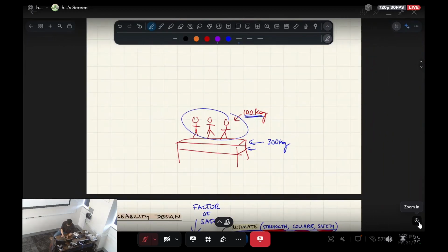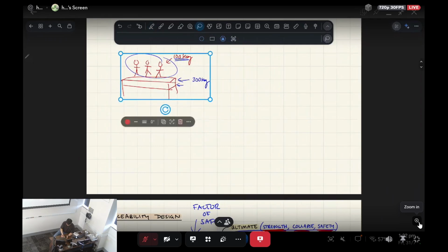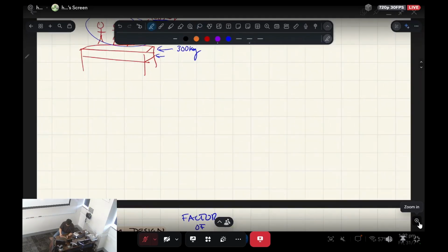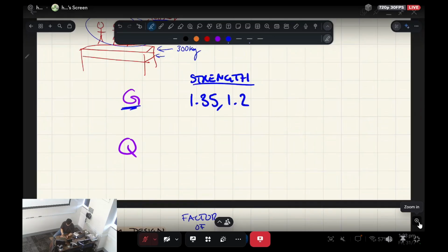And I'll give you another quick explanation on how we exaggerate or under-exaggerate these loads. At this point, you're probably pretty familiar with the concept of a dead load and a live load. Under the philosophy of strength-based design, you know that we have these exaggeration factors like 1.35 or 1.2 for dead load, and we also have exaggeration factors for live load, right? Under service loads, these are either basically unfactored or under-exaggerated in some way.